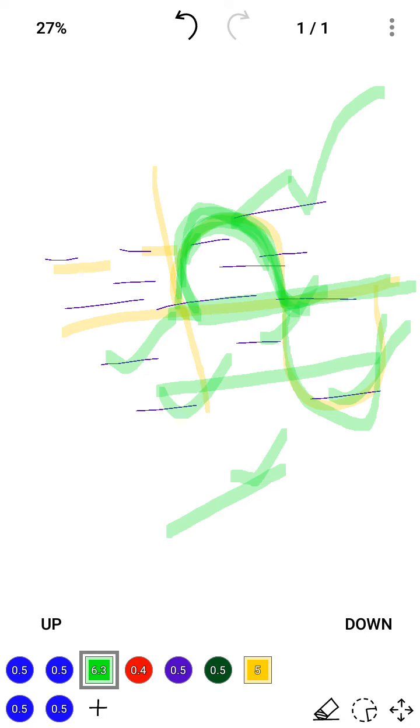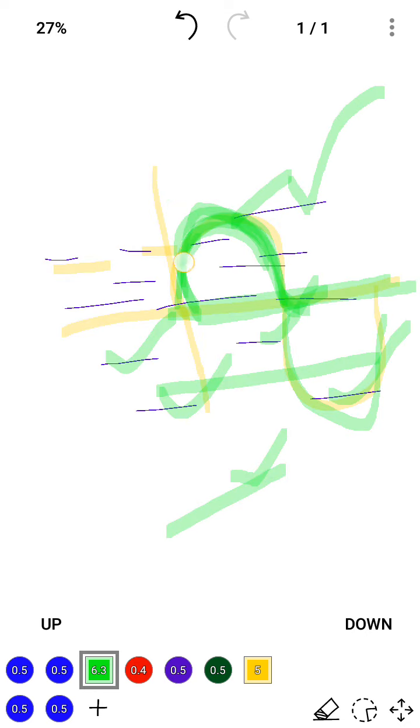Because of this change in electron velocities, some electrons start later but go through the positive cycle, so they move quickly. Other electrons start before these late electrons but go through the negative cycle, so their velocity decreases, and they meet at one place. That explains the velocity modulation process.